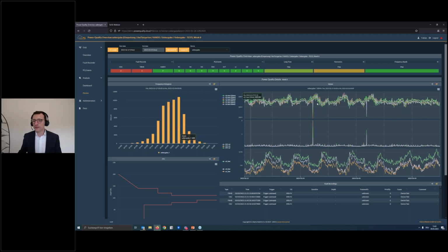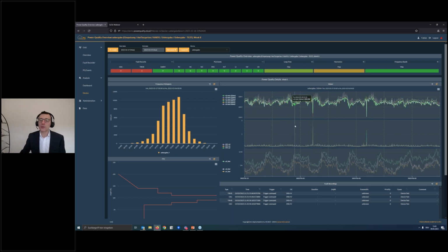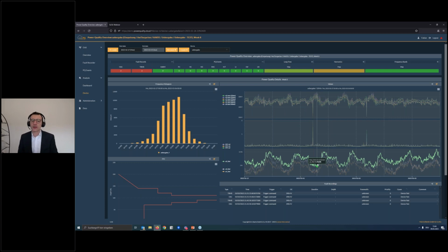For the voltages, it's looking like that, which means here, for example, we had 1 week of data sets, and we have maybe one small dip. And regarding this dip, another value, the so-called flicker value, the PST, is automatically rising up, automatically increasing its value, and below we have also the THD value, where you can see our lifetime a little bit.